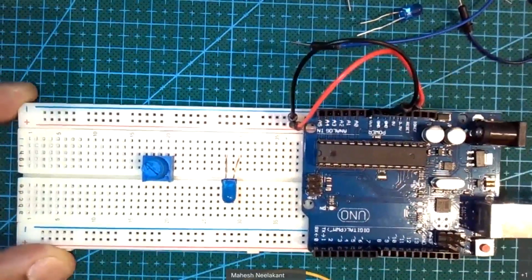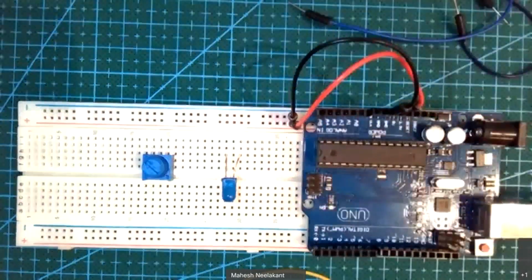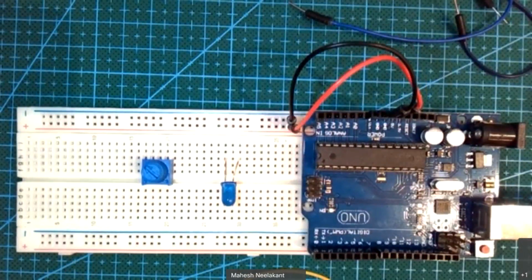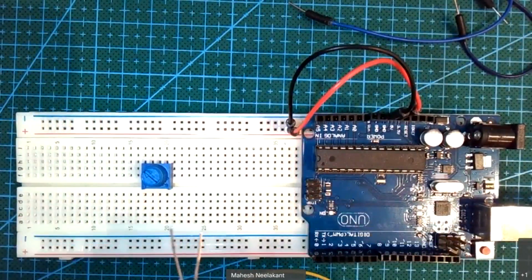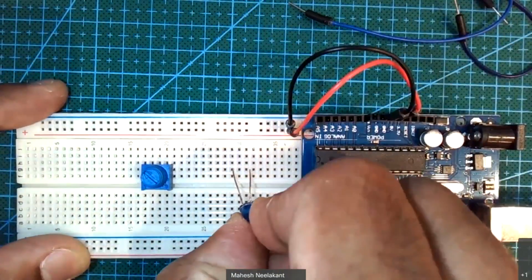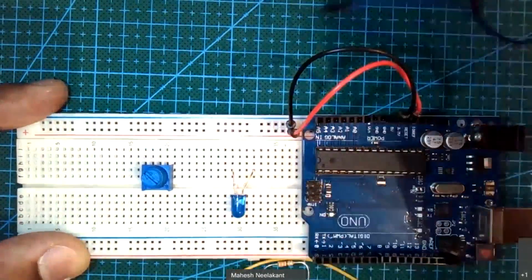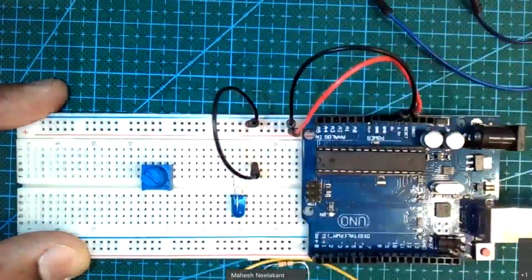And so the next thing in the diagram that it tells me to do is wire up the LED. So let me go find my LED. Oh, my LED is already in here. I forgot about that. So I'm going to connect up. It says go ahead and connect up black to the positive and negative. Remember I told you in an LED the positive is the longer one and negative, or ground, is the shorter one. So I'm just going to put that in there. I'm just going to point it down so you guys can see it being wired up. And connect up ground right there.